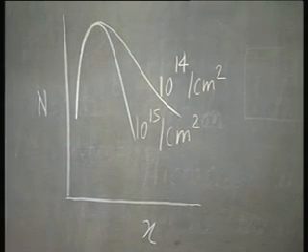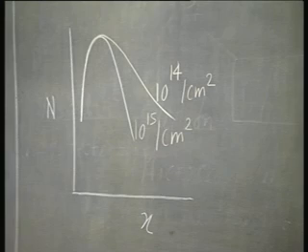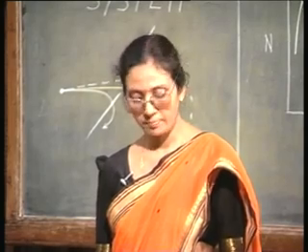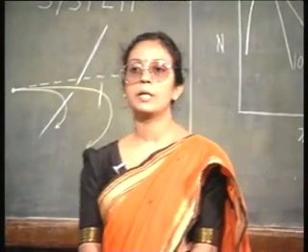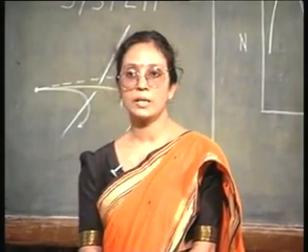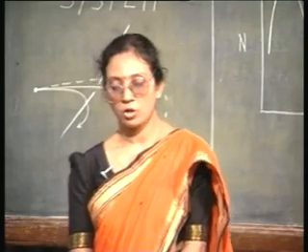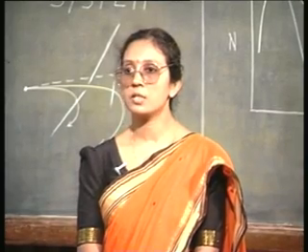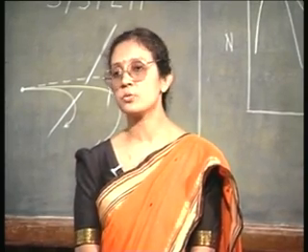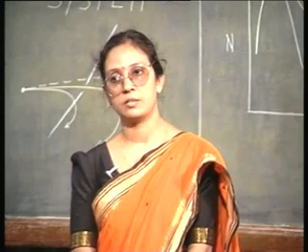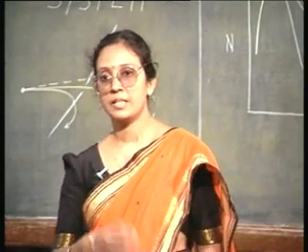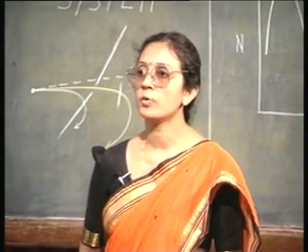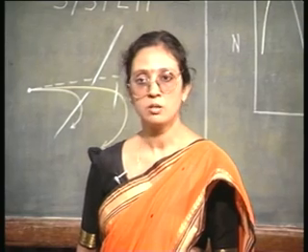That is why sometimes prior to implantation, silicon is pre-amorphized by self implantation or by an inert implantation. You can either implant argon or neon, or you can self implant, that is you can implant silicon on silicon, in order simply to amorphize the region, so that in that amorphous region when you next carry out the implantation, the profile will resemble a Gaussian more closely.